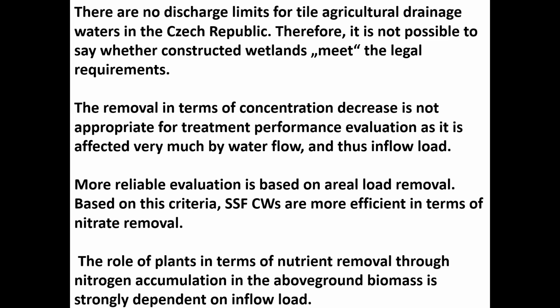The higher the inflow load, the lower the role of plants, because there are certain limits for nitrogen and phosphorus that can be taken up by plants. And if you increase the load, then we do not increase the accumulation. So if we have very lightly loaded systems, then we probably can achieve a much higher effect of plant removal.